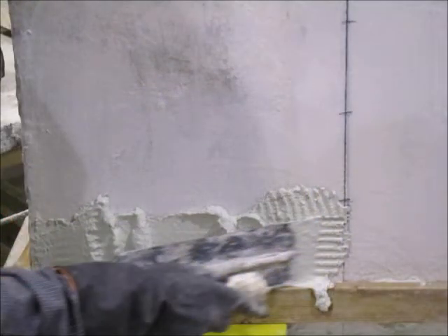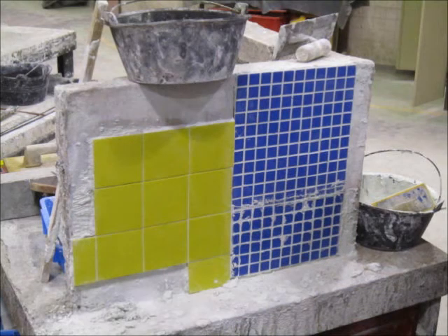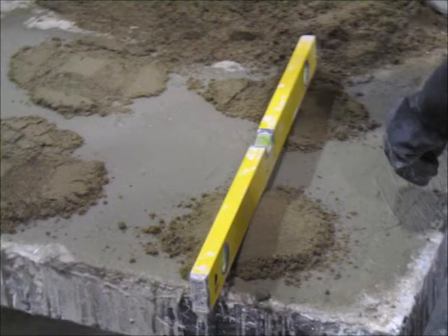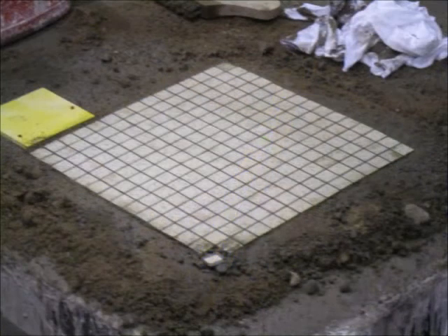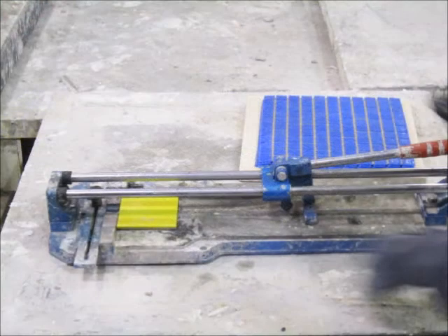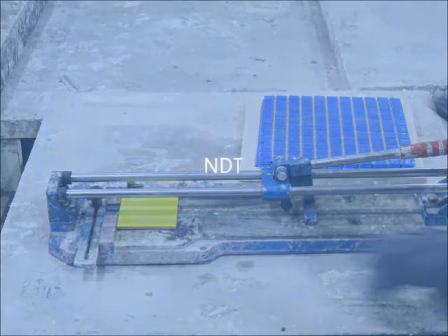We are also required to learn plastering, wall tiling, and floor tiling. When doing wall tiling, we place cement paste both on the wall and the back of the glazed mosaic tile, and then put the glazed mosaic tile on the wall. Also, we can use cutting machines to cut the tile into a suitable shape.